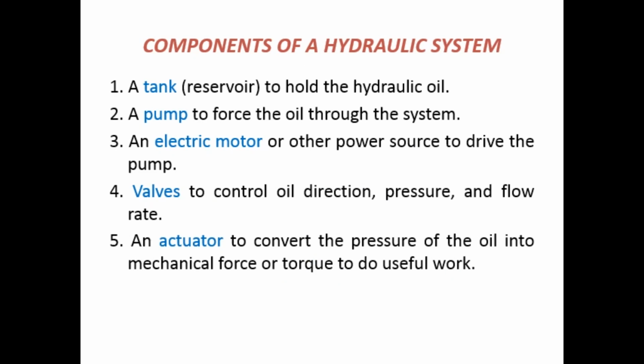Now let us talk about the components of a hydraulic system. In case I want to build a hydraulic system, what are the basic components that are required? These components are the basic components which are a must for any hydraulic system. It consists of a tank, and the function of the tank is to hold the hydraulic oil, because oil or water or any liquid medium is used in a hydraulic system. So the first basic component is a tank or a reservoir, which is meant to hold the hydraulic oil.